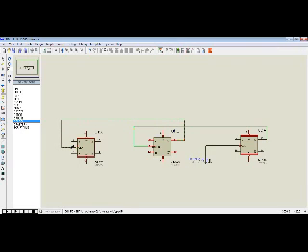So those are the clock signals. Then we need to connect the JK inputs to a high. We can use a DC source, and in all of them, we make sure that the inputs to the JK flip-flops are high.